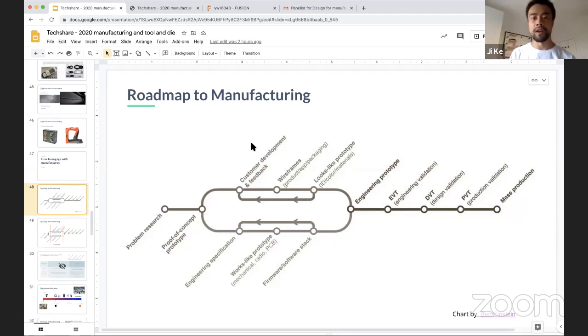How far is that from where the injection comes in, and what kind of plastic is it? Does it have draft angles? Can it be ejected without breaking? How much tonnage does your machine have? If you have a bit more detail, I'm more than happy to answer with a more solid answer.